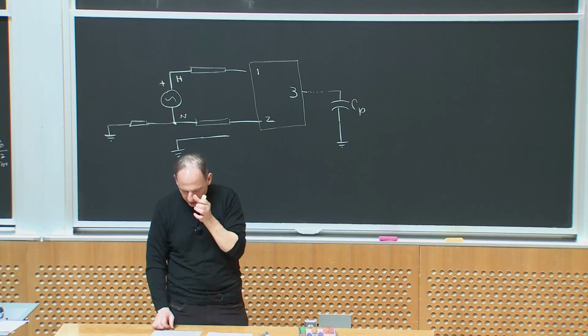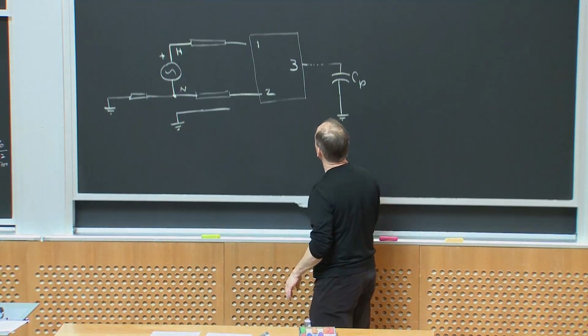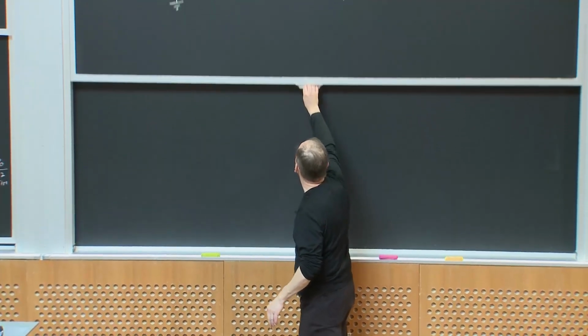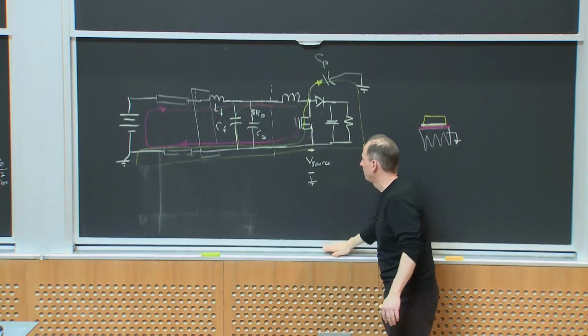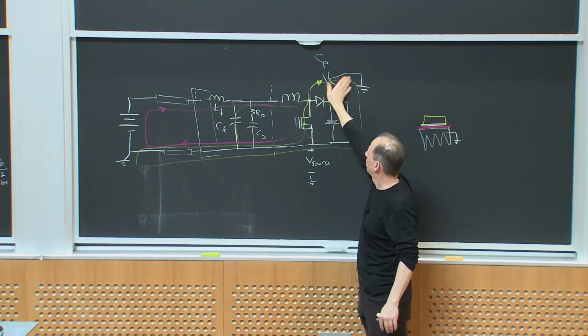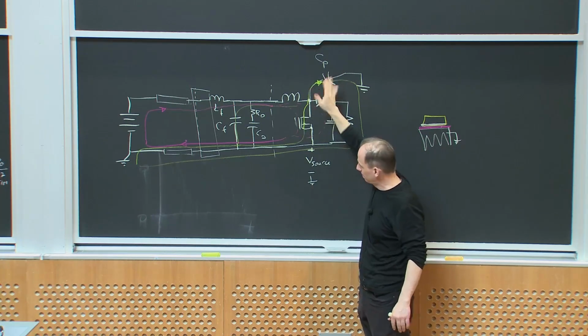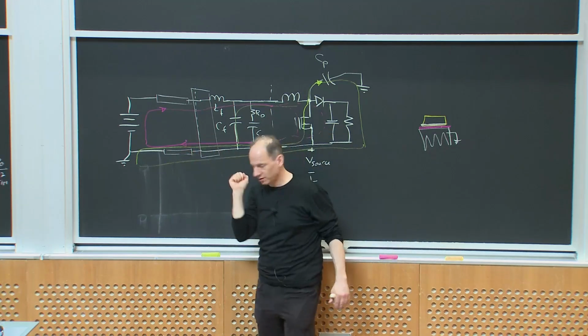I should have noted, by the way, and I'll come back to this, it's a little bit easier to see in the case of the DC case. If I've done this, and now I have very peaky currents coming through this parasitic capacitance, I have high frequency currents flowing on this lead, right?